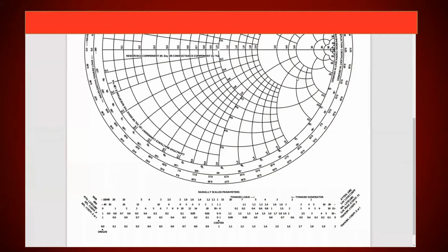But now, remember the chart that I showed you before? On some printed Smith charts, you'll see this stuff on the bottom, and it's really just the same chart. You draw a line from the origin all the way down here. That's 1-to-1 SWR. It's infinite return loss and so on. It's really the same thing. You can get your SWR, your gamma, your return loss, all from this chart. And it's nothing magical. It's just a different way of drawing a chart.